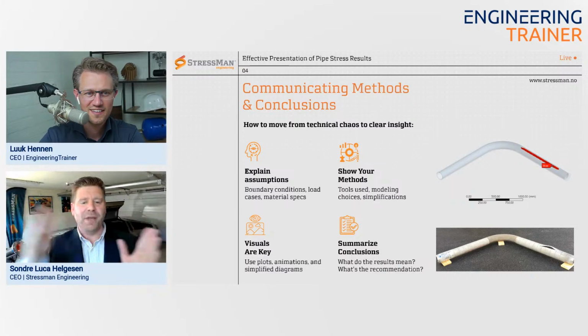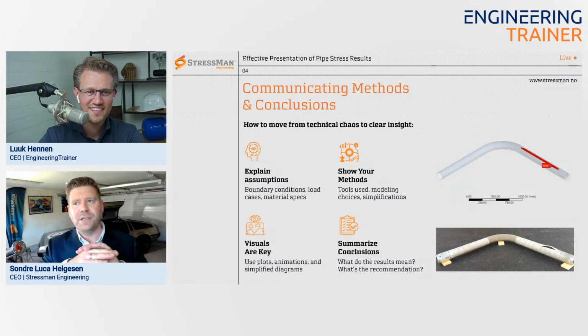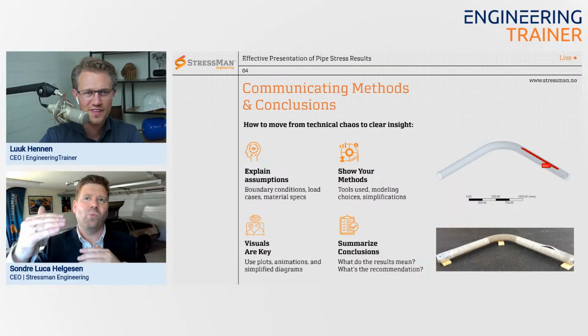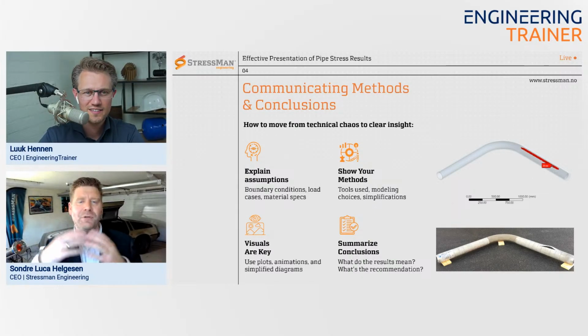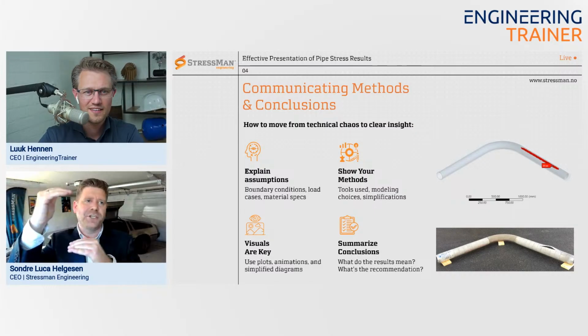We expanded the cases basically to have a lot of cases to reduce conservatism, and then we had a longer introductory text about what we are doing where, what we are using the various cases for, how we are considering the loads on equipment, and how we are considering the expansion stress ranges, for example, and so forth. So it's a very detailed explanation that maybe took half a page in front there. And of course, again,